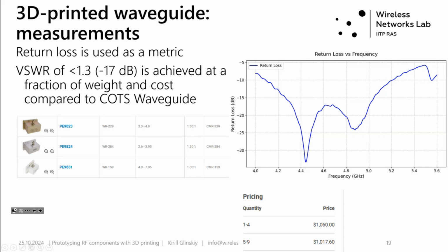For example, molding, where you just pay once for the molds, and then just for the machine. Whereas 3D printing starts off quite cheap, but then it doesn't get much cheaper after that. So we're talking about the price curves. Probably it would be more expensive, but still possible to manufacture it in thousands compared to the other approach.